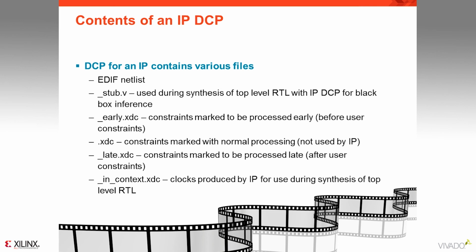The _late XDC file is for constraints marked to be processed after the user constraints, such as constraints from the _clock.xdc file. Finally, there is the in-context.xdc file, which provides clock creation commands to be used during synthesis of the top-level RTL as explained previously.